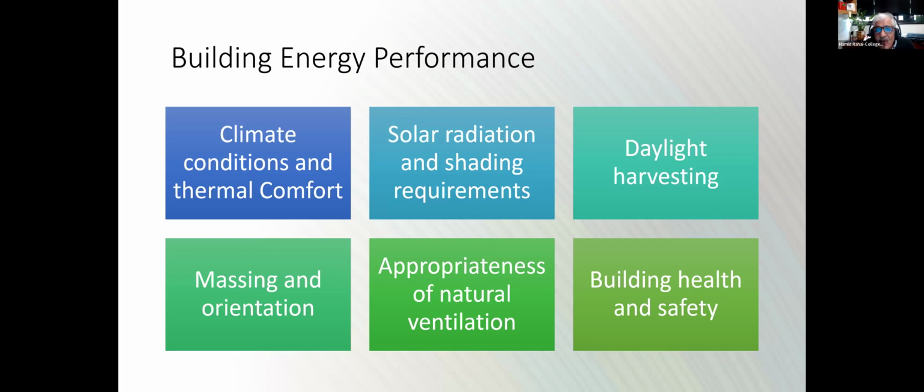So when you do any BEP, Building Energy Performance Assessment, you can play around with that based on the site that you have, for example how you can reduce direct solar radiation in California. Obviously, if you are in a cold environment, you want to increase that. And then what kind of shading do you want to have? Outside shading? Inside shading? Is it automatic shading? Do you want windows that have films on them that can cut down radiation, and so on.